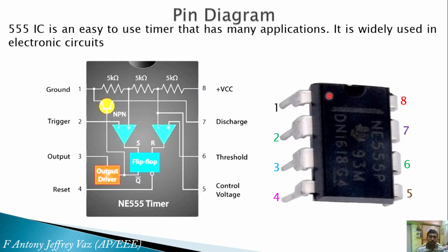You have to look to the left-hand side, then this will be the first pin. Okay, you see the curve over here towards your face and check, here is the first pin. From this you have to count 1, 2, 3, 4, 5, 6, 7 and 8. For all integrated circuits, this is the order of pin numbers. You have to do it this way.